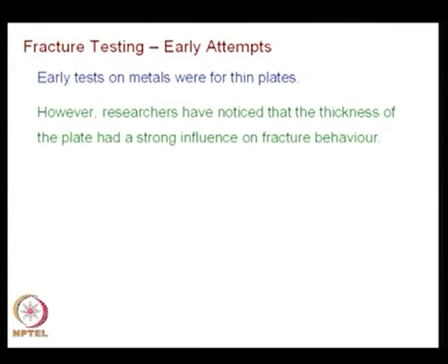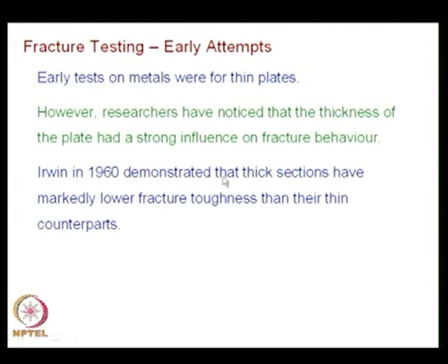Initially they worked on thin plates, then they noticed the thickness had a strong influence, and Irwin in 1960, mind you this is one of the early stages of fracture mechanics development, demonstrated that thick sections have markedly lower fracture toughness than their thin counterparts.